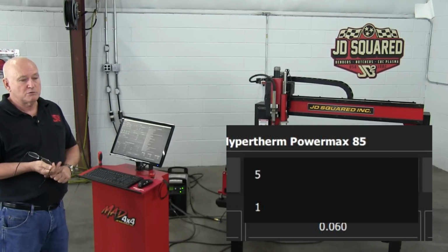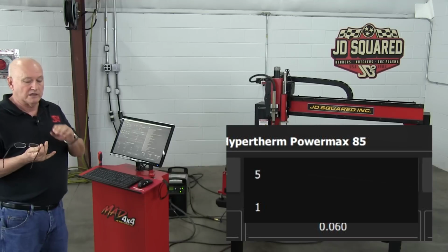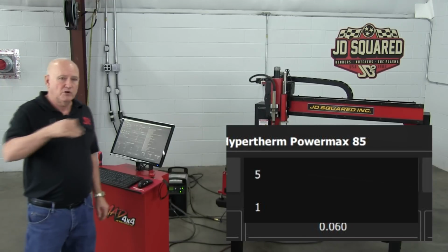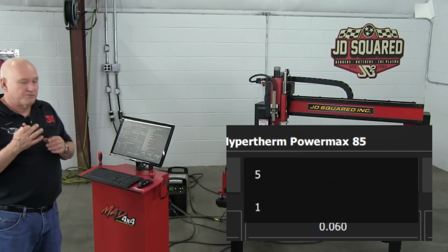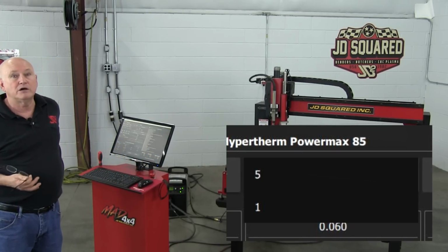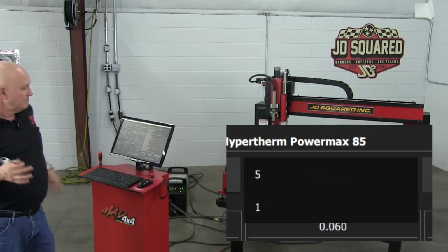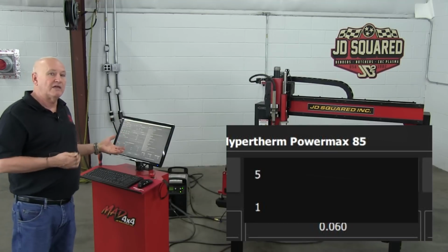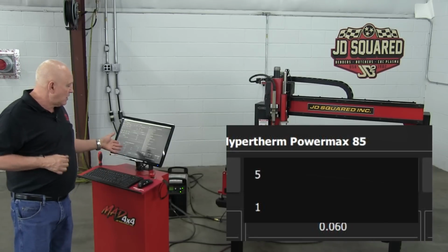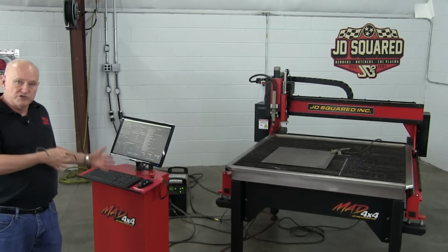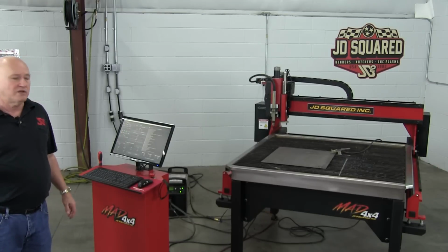Well, the plasma manufacturers will generally give you 2 qualities. Production, which means I want you to cut about as fast as you can. Give me an okay cut. I can live with it. Setting 5 is give me the best cut you can make in this particular metal. So we have already preloaded all that information from the manuals and everything. Now, quality, in version 2 of our software, you can create your own tables.